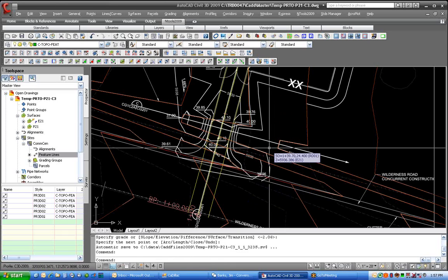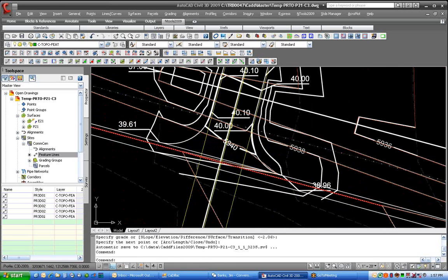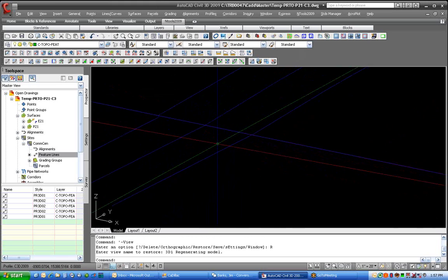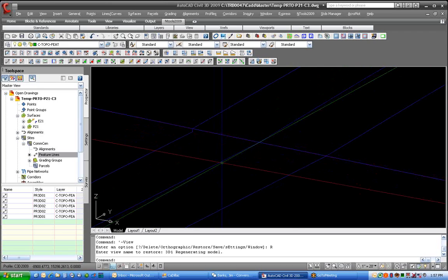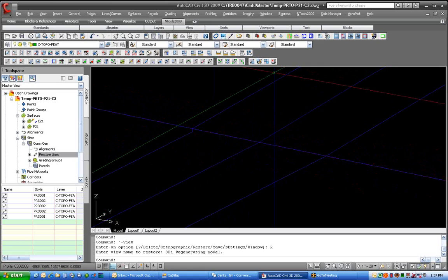All right, so now I have a feature line for my roadway. And where they actually intersect here, these yellow lines should be snapped up to where they match. Okay, so you can see I got an elevation change here, so those match now where the roadway one intersected. Okay, so again, taking advantage of that hierarchy and how it applies those.